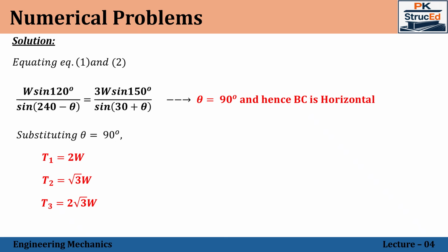To conclude today's lecture, always identify the point of impending motion. Draw clear free body diagrams. If there are any string problems, apply equilibrium at each joint, considering the joints as free bodies. And the geometry and trigonometry are equally important as the equations. In the next lecture, we will proceed with non-concurrent forces in a plane. Thank you.